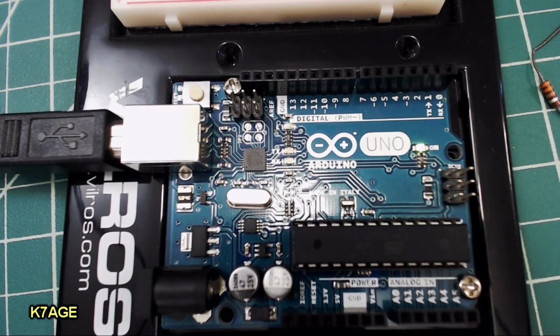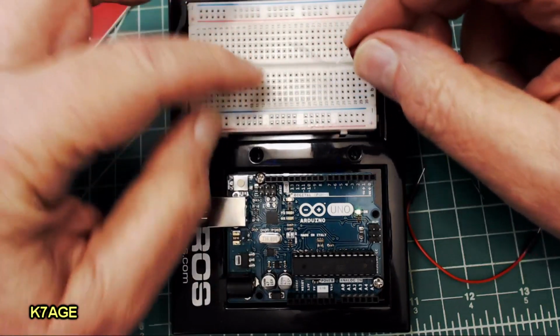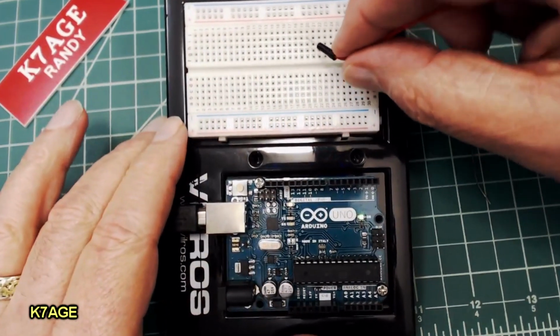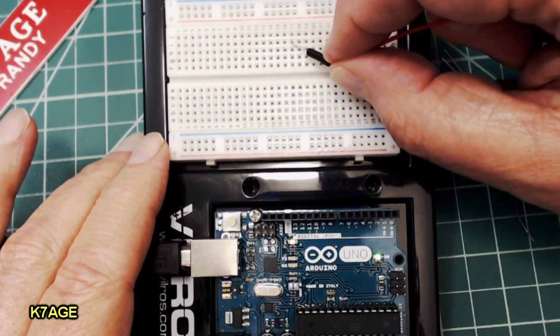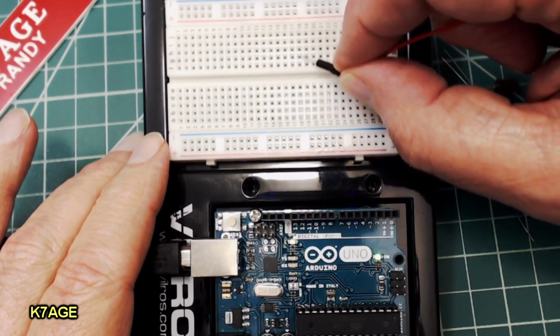So let me hook that up. Okay, so let's hook up our external LED. We're going to use the breadboard here to do that, and I'm going to use a jumper wire. And if you've never used one of these breadboards, these are pretty neat. There are these groups of 5 holes here that run in a row. So these 5 are all connected together, which are separated from the next group of 5.